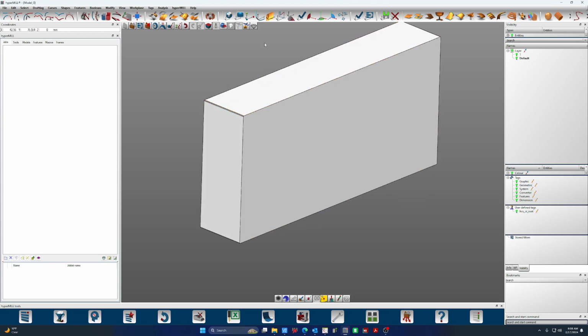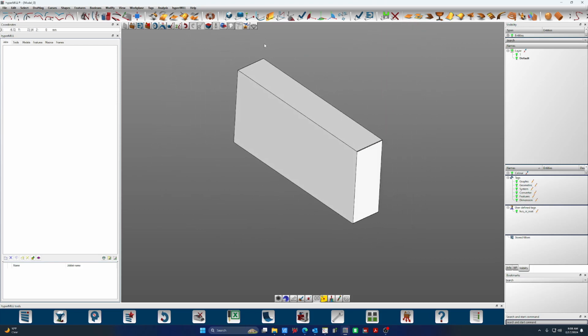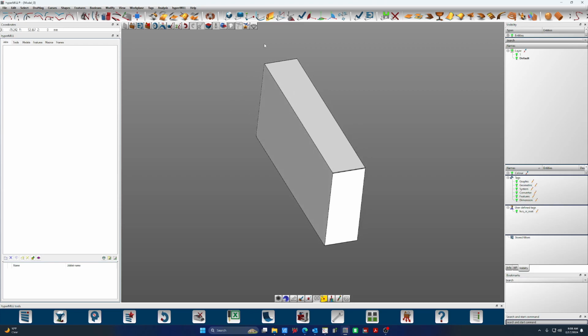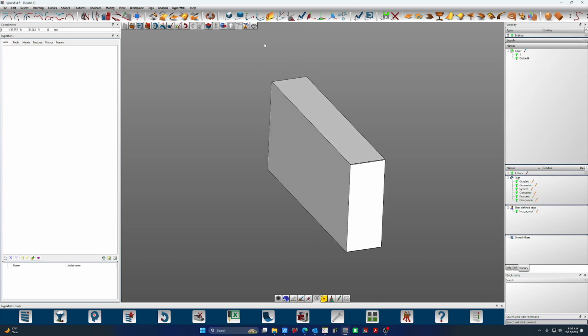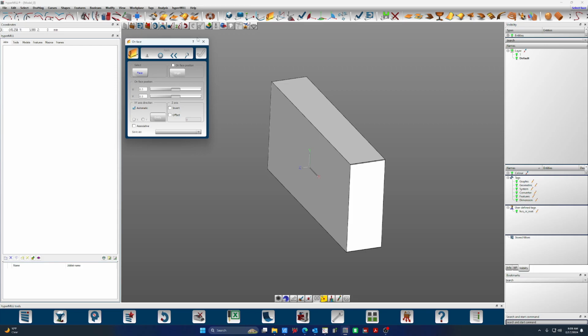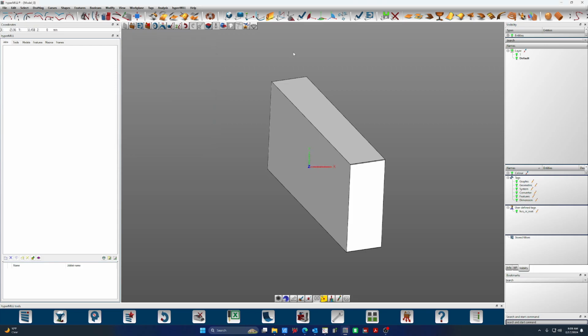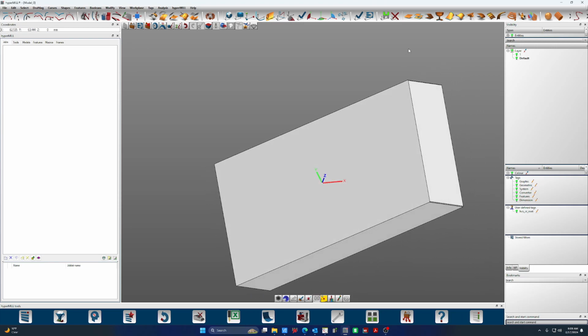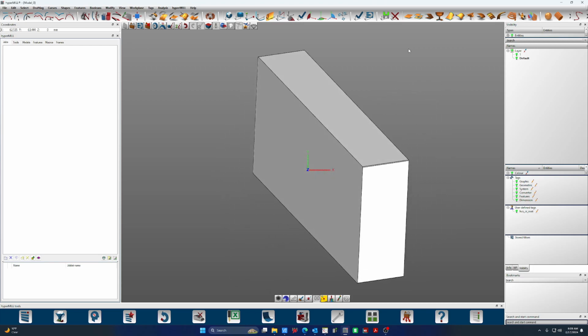So that's all of those times, particularly in the 5-axis workspace, where if we envisage ourselves as the spindle and we're looking through the tool holder down at our model, we're kind of establishing like, yes, this is the vector that we want the tool coming from. We could quickly snap a workplane on that face, okay? And then if we use the V key, it has now oriented that workplane normal to our view. The other one we're going to learn to live and love, Control 1, that is view normal to workplane.